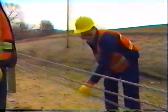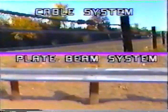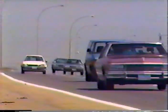The problem may lie in the balance of strength and flexibility of the cables or the plate beam, in the bolts that attach the cables to the post, in the depth and positioning of the anchors, in the size, number, or type of posts, or in the slant of the end piece. The whole system must provide the right balance of strength and flexibility in order to prevent a vehicle from snagging into part of the system or being forced over, under, or around the system with such a force that serious injury and extensive damage are likely. The right balance provides passengers and vehicles a continuity of movement at a speed and distance that provides safety.